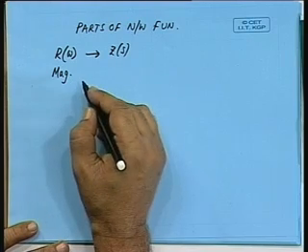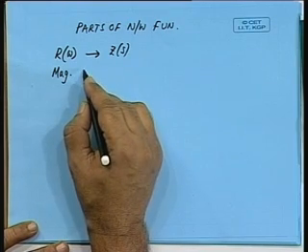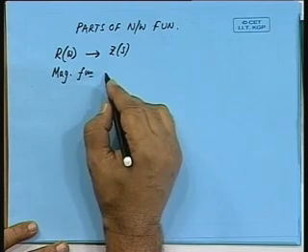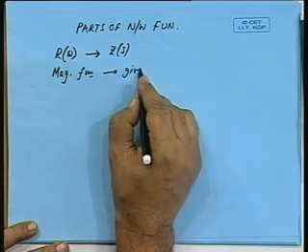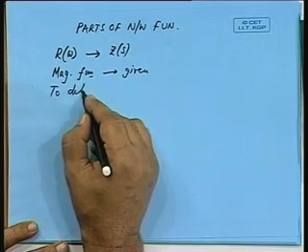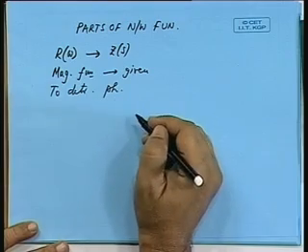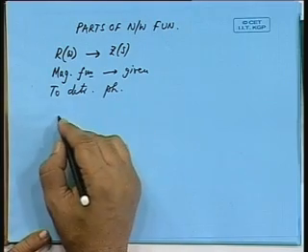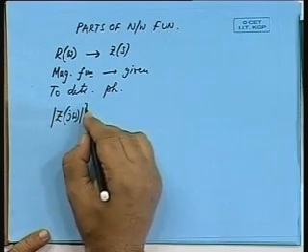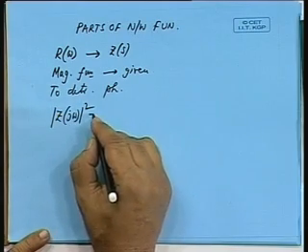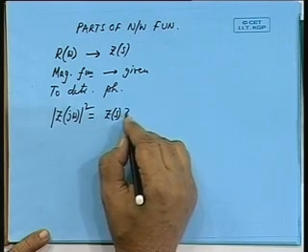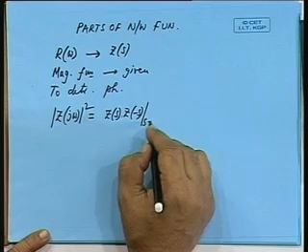Now today we shall be discussing the magnitude function. If the magnitude function is given, how to determine the phase. Now the magnitude, |Z| squared, can be written as Z(s) into Z(-s) at s equal to j omega.